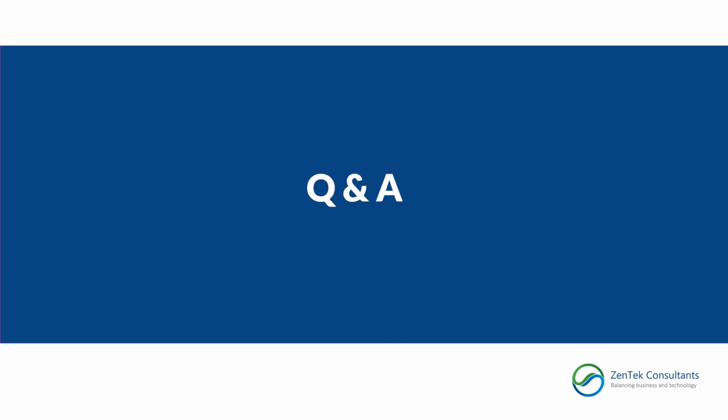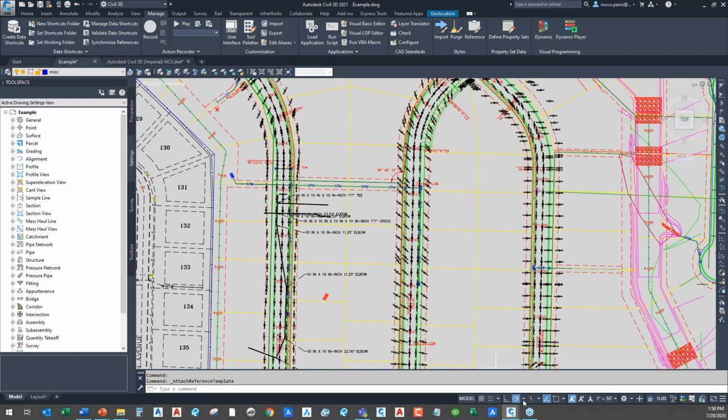Oh, yeah, for that, Victoria, like I said, the key with that, because it's really gotten back to more of just a base drafting instead of the compass rose, what I had set here is I had actually gone in, I'm using just polar tracking, and I just set the 11.25 as my current default, so that as I'm drawing, everything's being locked down into those. So even if you do a polyline, when you go to draw it, say the green line is give me every 11.25 degrees, so that I can easily set to the right angles. That's how I worked with that.